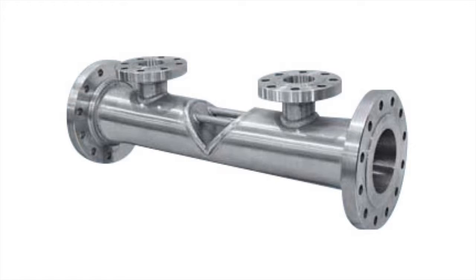However, this type of differential pressure flow meter technology can be constructed to work as either a gas or a liquid flow meter. Wedge flow meters are highly robust and resistant to wear. They offer the solution to measuring dirty, viscous, or abrasive flows, as well as those where there is a risk of fouling. This enables them to be used in applications which could quickly render other types of DP flow meters useless.